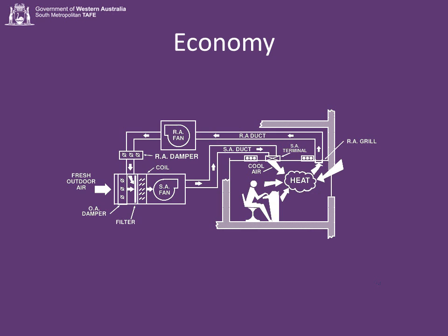The other thing to bear in mind is return air, which is air that's been breathed out, is often full of other things. It's full of carbon dioxide, it's full of moisture, it's full of farts. So it might not be a wholesome, pleasant air. Sometimes, if the return air duct is not particularly well designed, we need to give the air a little bit of encouragement to come out of the room. So we might have a return air fan drawing the air out.